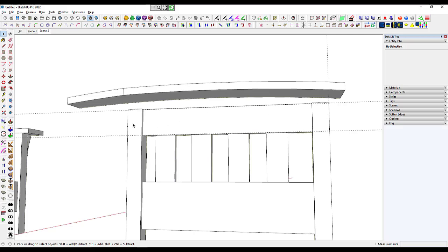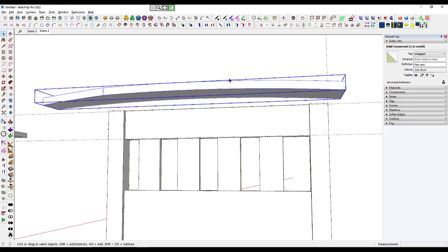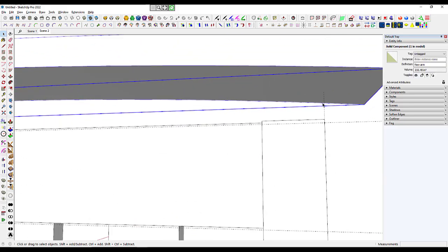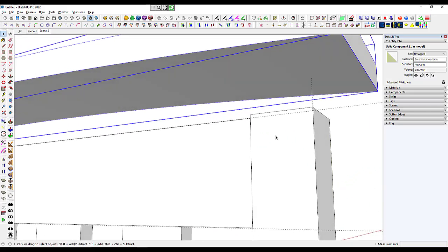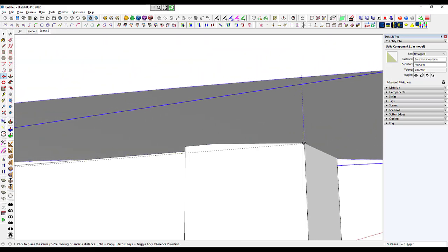So now in order to transfer the curve from the underside of the armrest to these parts, I'm going to go ahead and place the armrest component where it needs to be. So I've got this vertical guideline, and I'm going to use the move tool. So that was M. I'm going to go from where the guideline goes through the face. I'm going to bring that down to